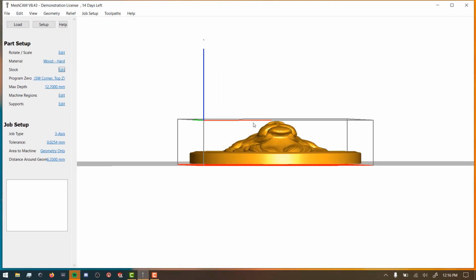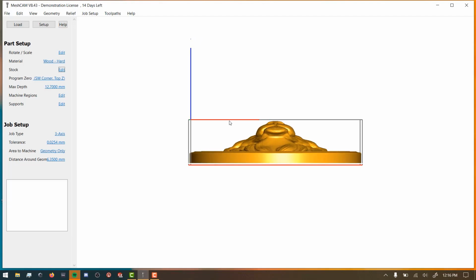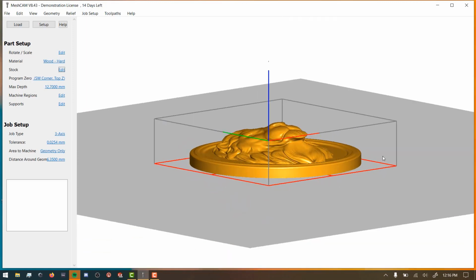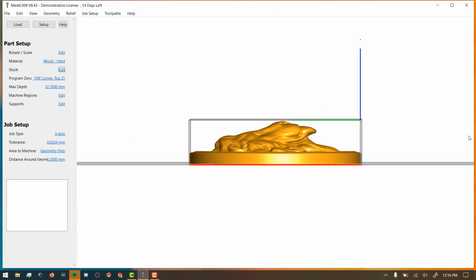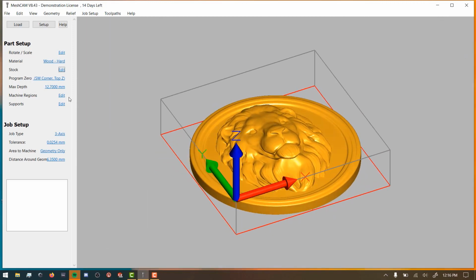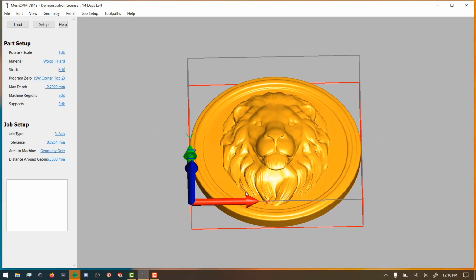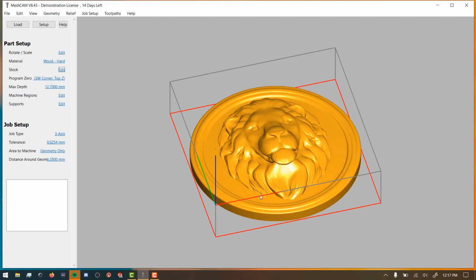And we can see here it has now added that little tiny bit of extra geometry there, because that is how thick the wood is that I want to work with. Perfect. Okay, so I'm going to be okay with where this point is, because in the machine later, and we'll talk about that, I'll move the machine to more towards the middle of the working area and set that as my 0 so that I know exactly where this is going to cut.